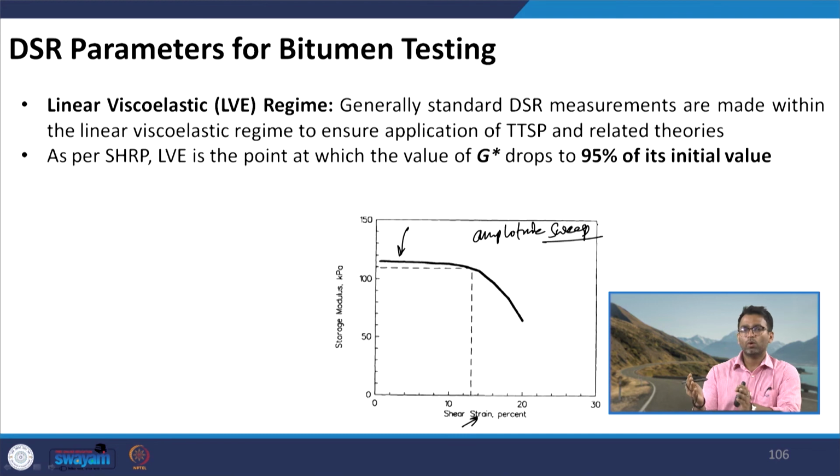If you remember from our discussion, when the materials are under small strains, we have the same graph for modulus or stiffness, is it not? And then we had other curves which were on the lower side, but with higher strains. So, individual curves we had, if you remember from the last presentation. Therefore, what we are expecting is that within the linear viscoelastic regime the modulus does not change with change in strain amplitude. That is what we are trying to find here.